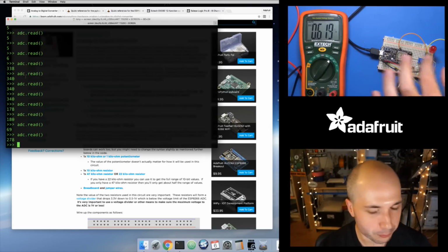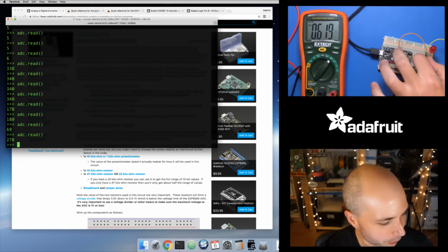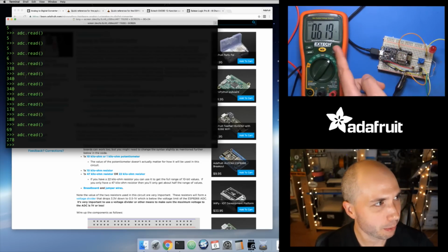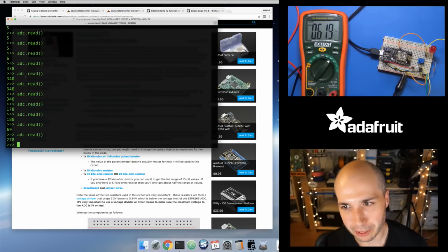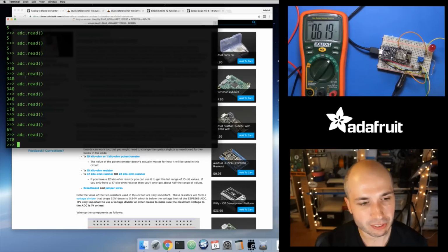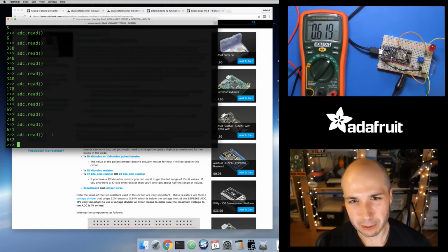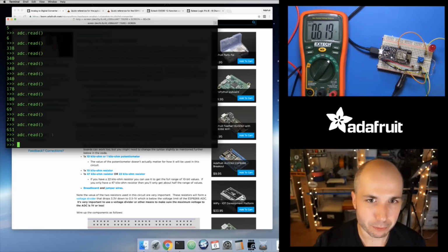So it's not the full 1 volt, just because the divider isn't exactly cutting it down to 1 volt. But this is good, at least I see I'm only sending 600 millivolts, so 0.6 volts in, so it's under 1 volt, so I'm not going to damage the ESP8266. Now if I call adc.read, notice I'm getting higher values, like 651 right here, and it's actually pretty close to the voltage value in millivolts, because that range of 1023 versus 1,000 millivolts in 1 volt, they're pretty close. There's a little bit of error there, but this seems like I'm getting the right values.